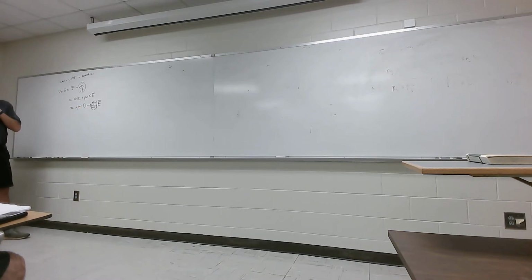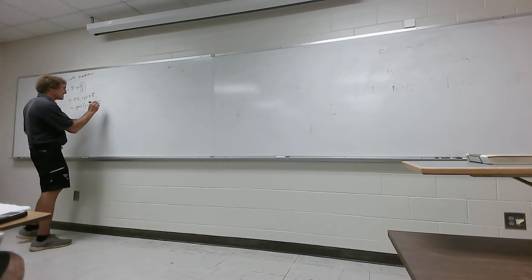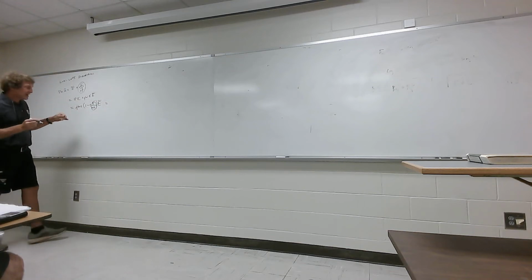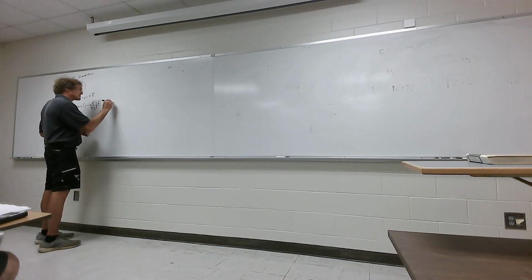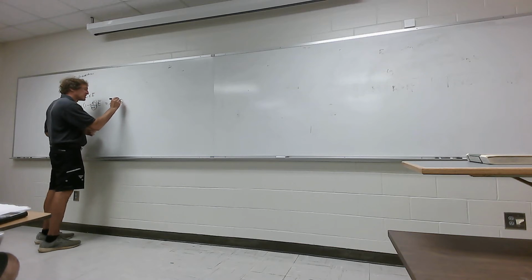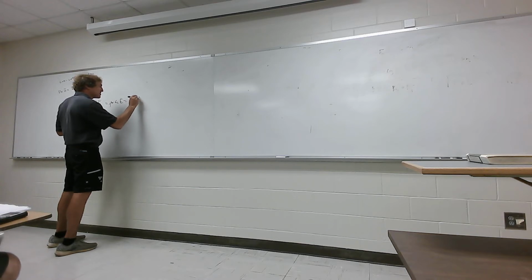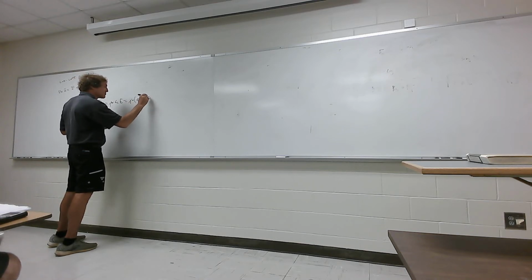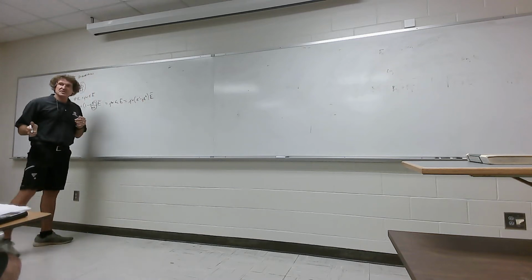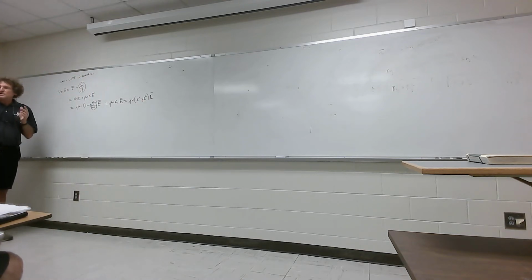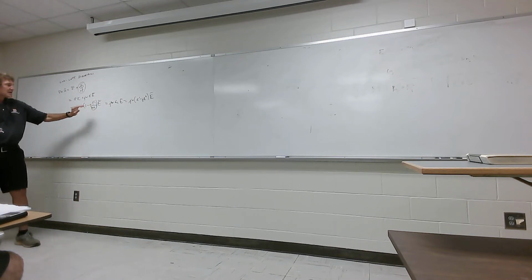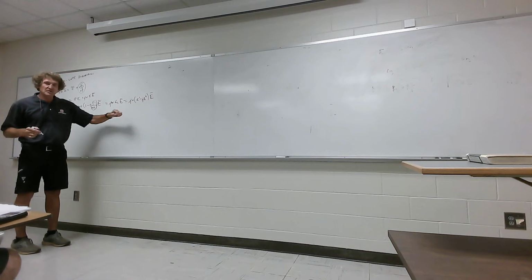Now, we don't have a sigma that allows conduction. So the way they actually write this is, we're going to have j omega, and it's going to be epsilon complex times E. And here, epsilon complex is going to be rendered as epsilon prime minus j epsilon double prime, times E. Try to appreciate what we're doing: we're trying to distinguish between actual current loss, which is the sigma, the real sigma. So we don't have that, but we have something that looks just like that. We have minus j times something, we call that epsilon double prime.